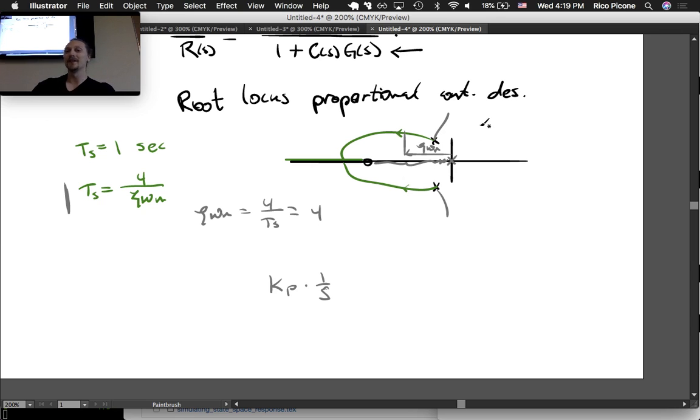So instead of doing that, what we'll do is we'll put the integrator in, and then we'll also put in a 0 in pretty close. So we'll put that S in the denominator, but then in the numerator, instead of just having 1 in the numerator, we're just going to put in S plus, we'll start off with, it's really hard to choose this, I'll start off with S plus 0.5.